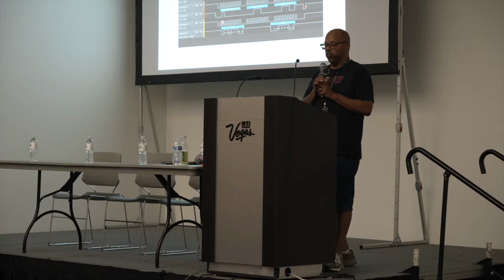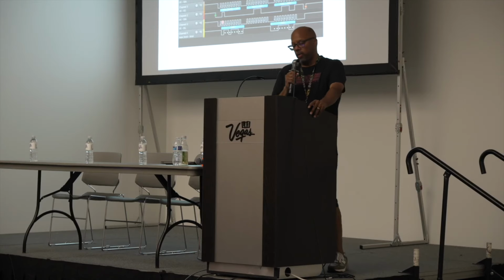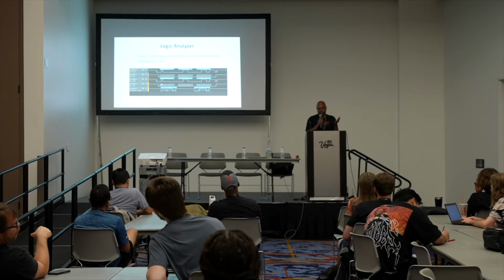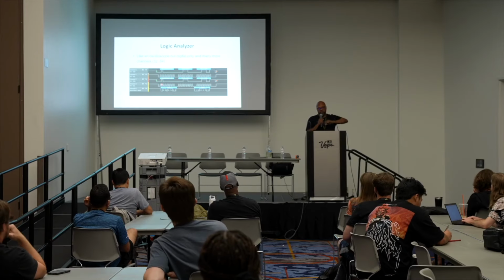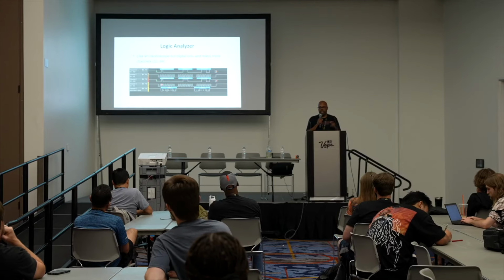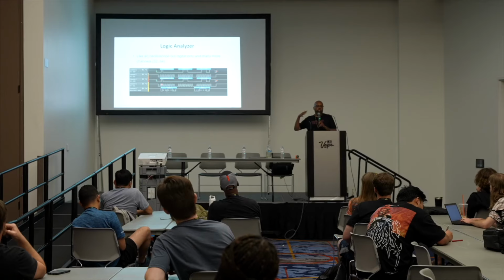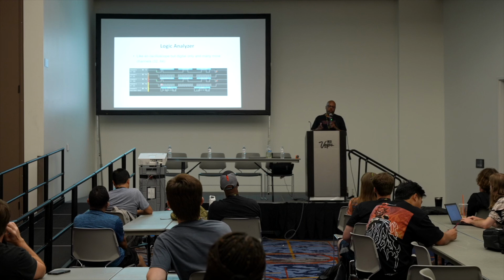Now then another thing that's really useful is a logic analyzer. Now logic analyzers, these cost even more, and the downside of a logic analyzer is that they are only digital. See, an oscilloscope's an analog device. It'll measure analog voltage. A logic analyzer only shows 0 or 1. Okay, it's only going to show that, so it's less information. But they have a lot more pins. They'll have like 32 pins, 64 pins. So you can see a whole bus at a time, right? A whole big bus, which is useful, but expensive.